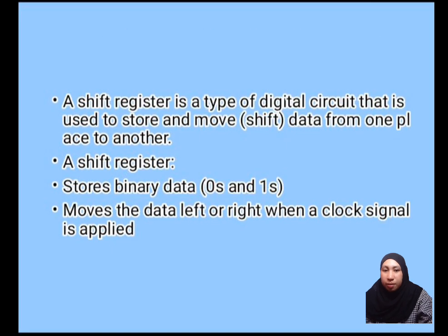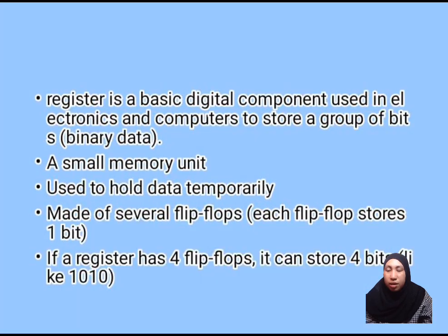A shift register is a type of digital circuit that is used to store and shift data from one place to another. A shift register stores binary data 0 and 1. It moves the data left or right when a clock signal is applied.